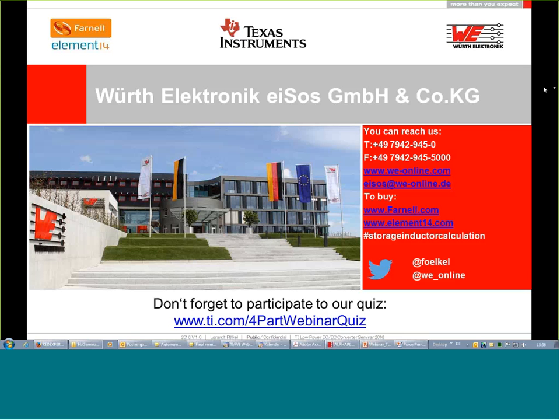And if you have a nice thermal camera, I did it myself first also, to try out if these tools really calculate correctly. I made the demo board, put it to the infrared camera, and measured the real temperature in the inductor, with all the dissipation from the PCB considered as well. I was really impressed that it was just 2 Kelvin difference between the RedExpert calculator and what I measured on the infrared camera.